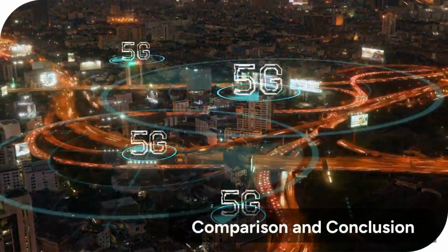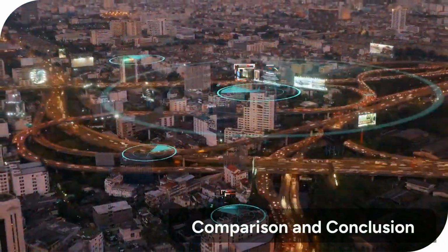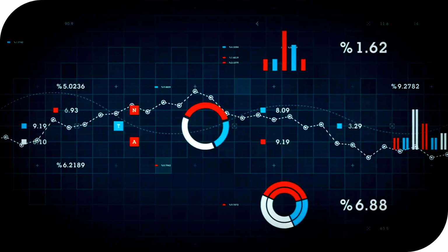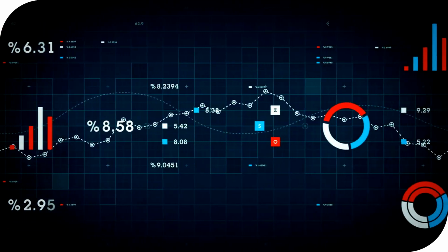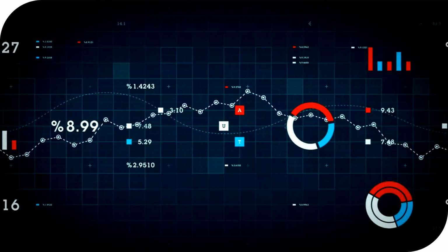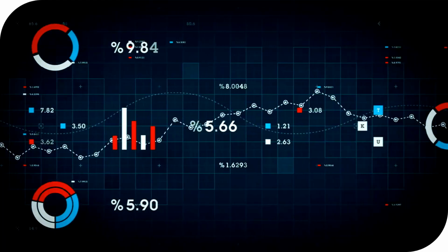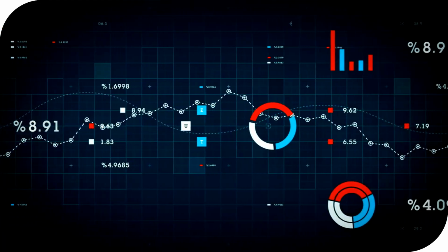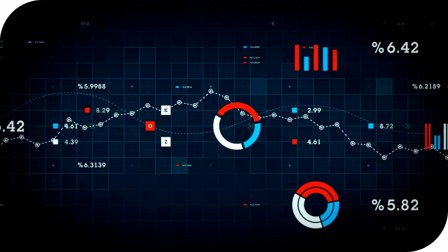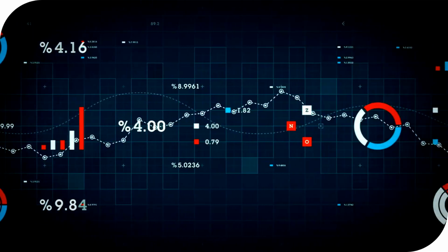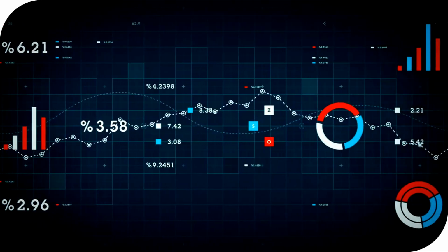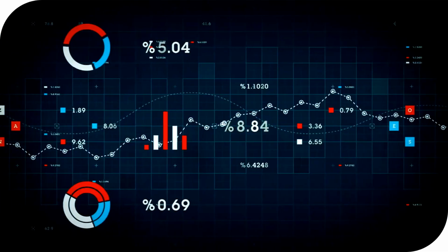We have covered a significant amount of advanced material, from Zadoff-Chu sequences in LTE to beam-centric access in 5G NR. To consolidate this knowledge, let's compare the two architectures. LTE utilizes cell-wide coverage, while NR is highly beam-specific. LTE relies on fixed subcarrier spacing. NR introduces scalable SCS. LTE primarily uses four-step RACH, although CFRA exists. NR offers flexible two-step and four-step execution. And finally, LTE RACH occurs across the full carrier, whereas NR access can be restricted to a specific bandwidth part.